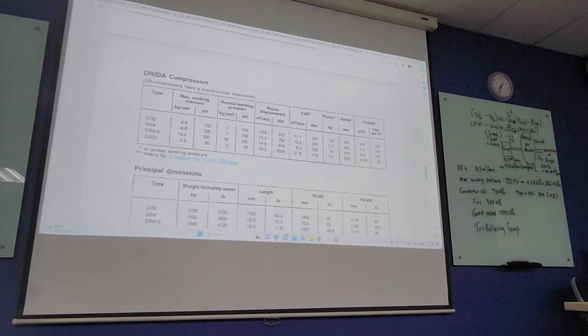Alright, to me it's wasted. Oh, okay. So in a way, yeah. I think a receiver is cheaper. This is what they claim. But it depends on you. If let's say you are rich, then okay, you can use this. Right, but the purpose of this is for us to design the proper air receiver to meet the surge demand. Okay. So this is the ideal design. That's why I want you to get this. Then subsequent questions relate to what you actually look at. Oh, okay.